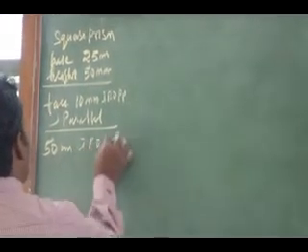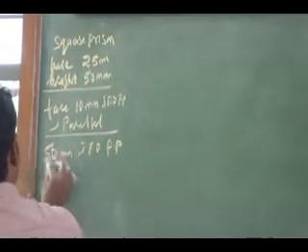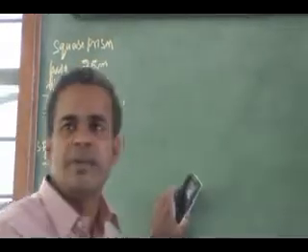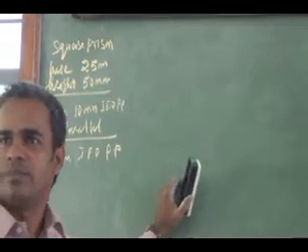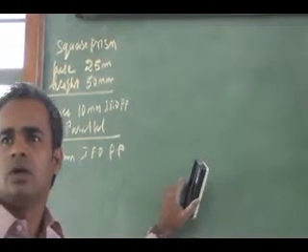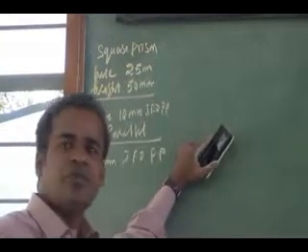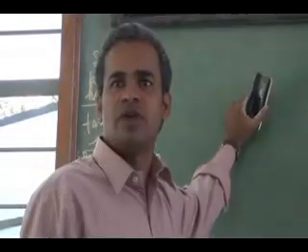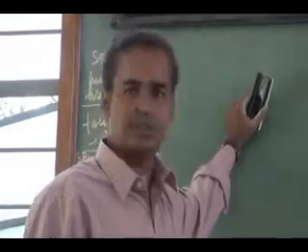So this is the station point. The station point is 50 mm in front of the picture plane, 75 mm above the ground plane, and 45 mm to the right of the axis.